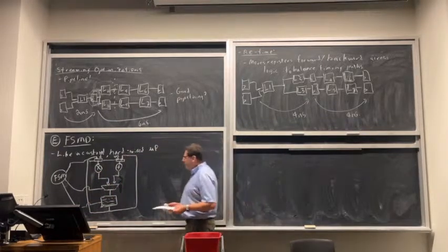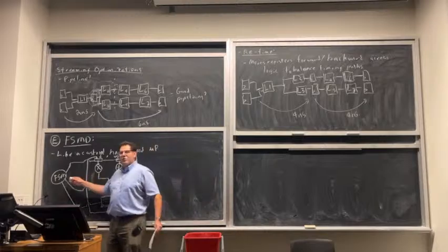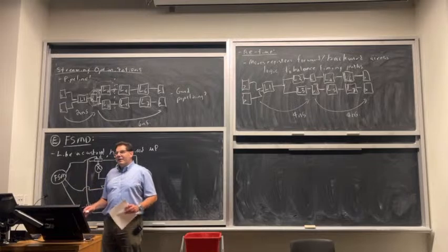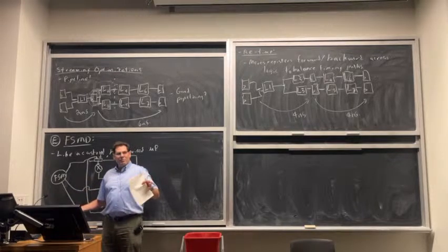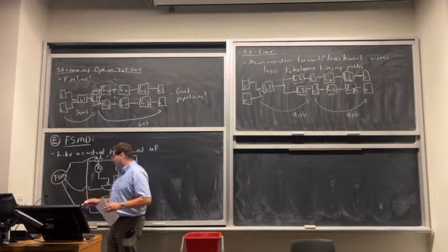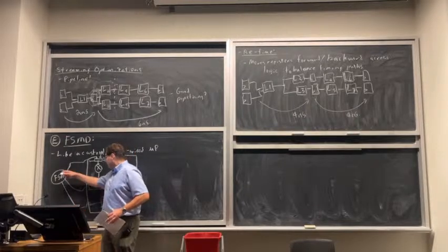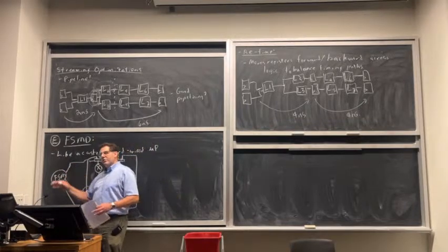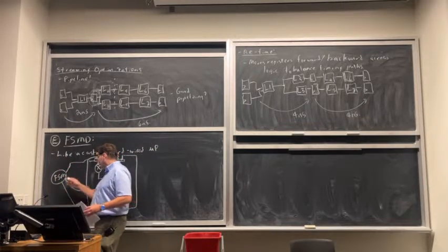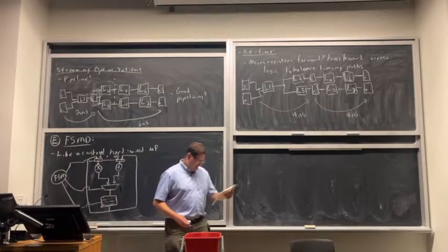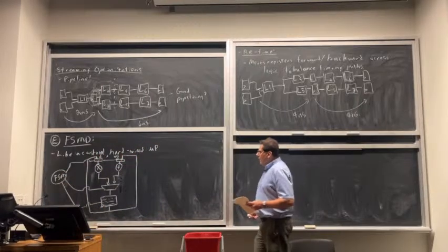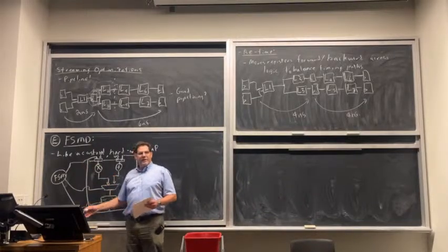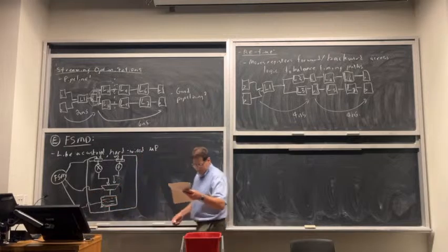And this is good for repetitive calculations. This finite state machine is just going to do the same thing forever. So this is not good if you had some huge long list of computations, or it varied over time, et cetera. Then an instruction stream is better. But let's say I've just got that quadratic equation and I'm doing it forever, going through the same few operations over and over again. Well, a finite state machine can do that, and it can do it essentially with less area than an instruction set if what you're trying to do is pretty repetitive.